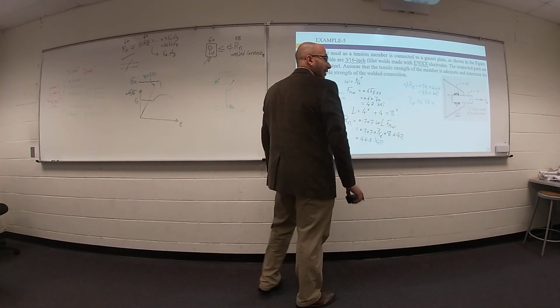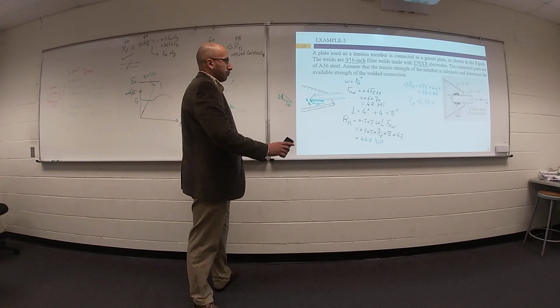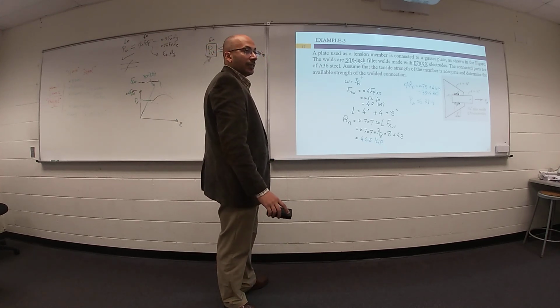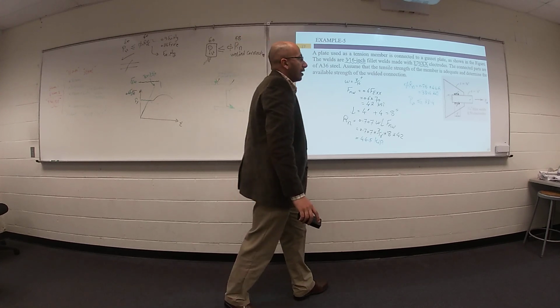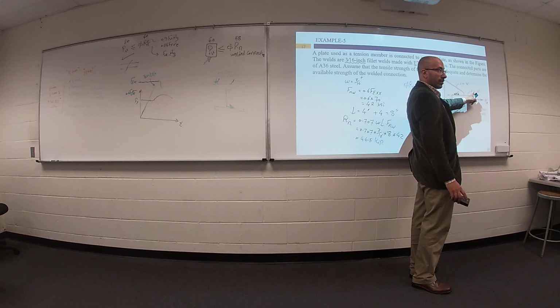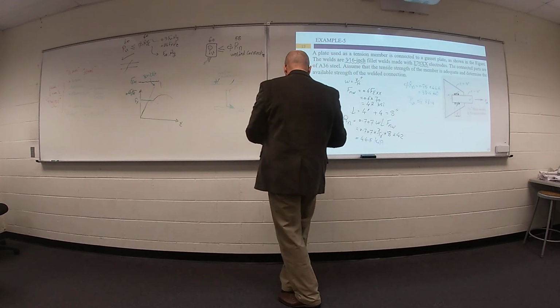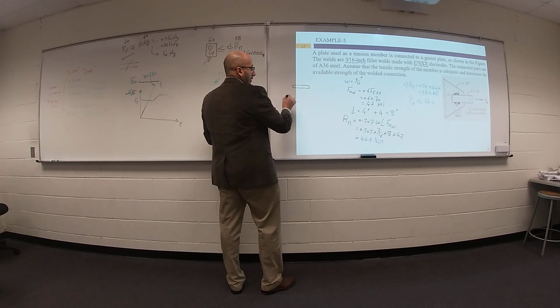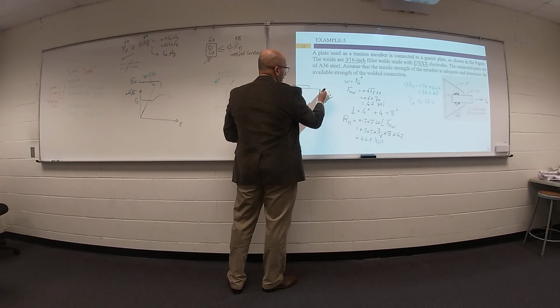Most people do start at. You can't go higher than a quarter though, right? On the weld first? No, you cannot. You cannot go higher than 1/4 because of the thickness of this plate. You can do something like this, and the other plate, something like this.